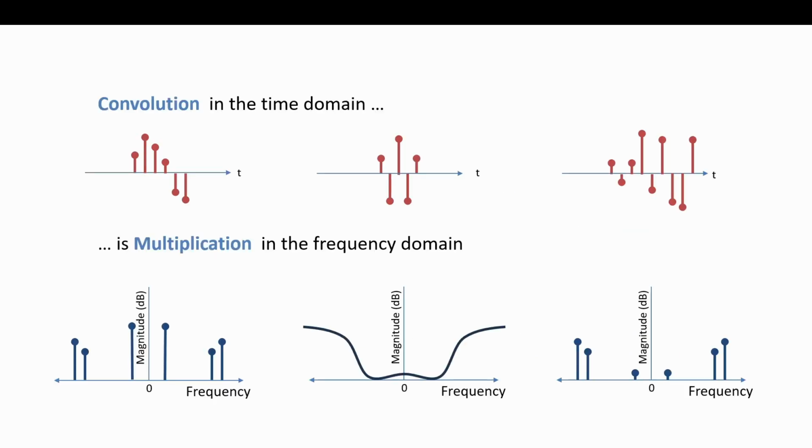So there we have the great property that convolution in the time domain that we talked about is multiplication in the frequency domain. That's pretty handy. So instead of doing all that convolution, if we can convert to the frequency domain, then we can just do a simple product in the frequency domain. What you're seeing along the bottom is a spectrum, centered on 0, centered on DC, just so you understand my graphics. And you're seeing a low frequency signal and a couple of high frequency signals.